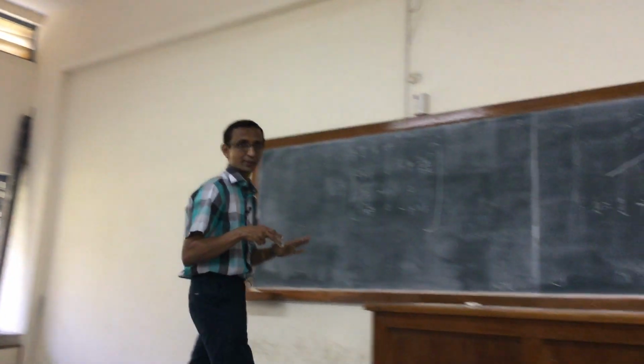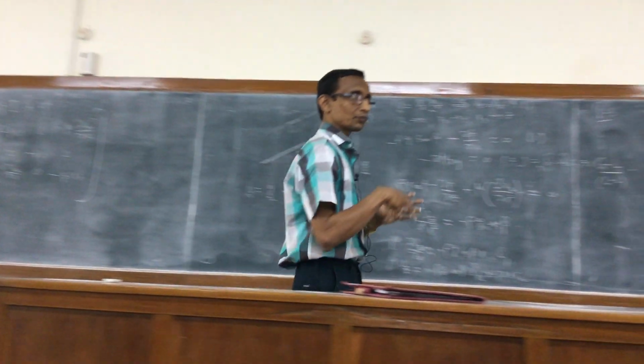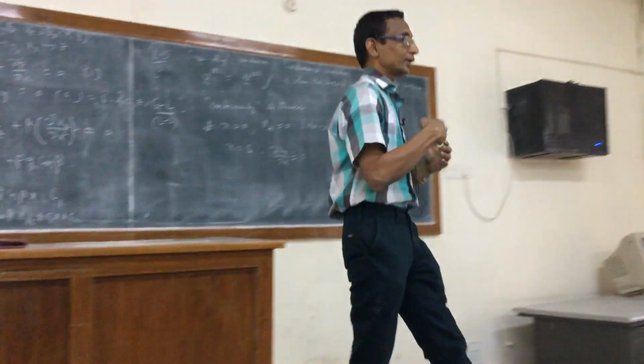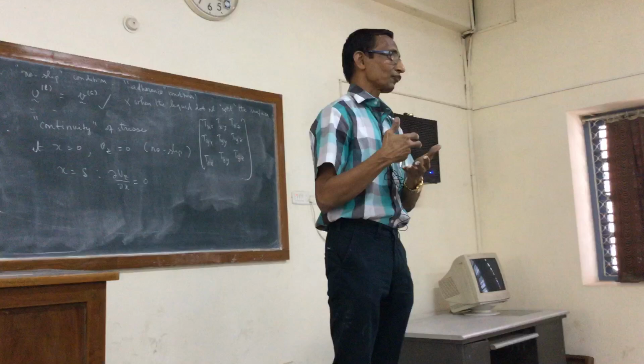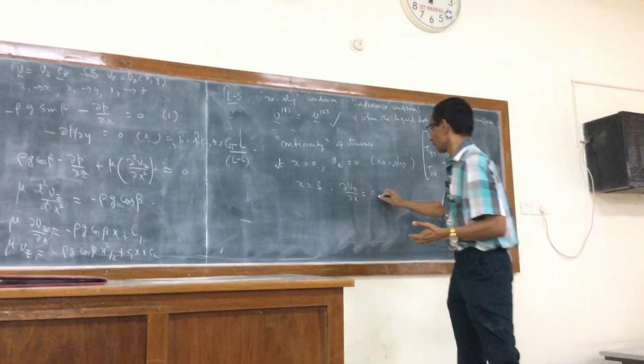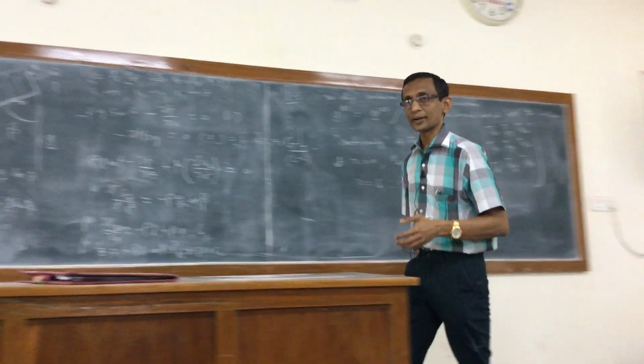Continuity of all the stresses across the interface. The continuity of the shear stresses means that dVz by dx for the liquid at the interface must be 0, and I can justify this condition.